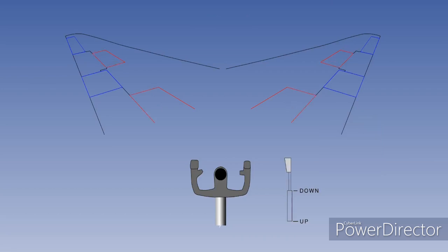While being used as speed brakes, the spoiler surfaces will continue to assist the ailerons with roll control. To illustrate this, we will pull partial speed brakes. Now, when a roll input is made, the spoiler surfaces will move up or down about the datum of the speed brake selection.